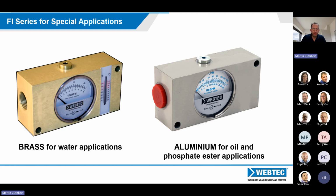And it also eats through the normal seals. So you can't use it with Viton or Buna rubber seals. You'd have to move to a different sealing technology. And here we use EPDM seals on this. So I guess the principle here is that the same sensors can be used for different applications, just we have to adapt the materials to suit.